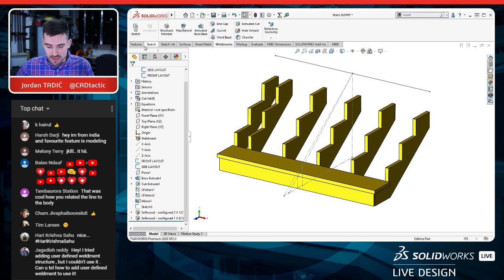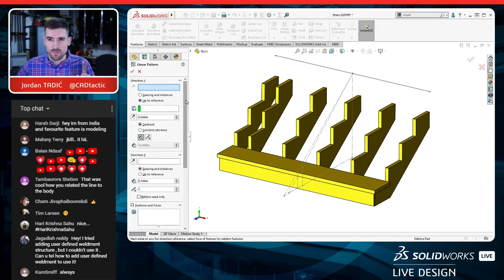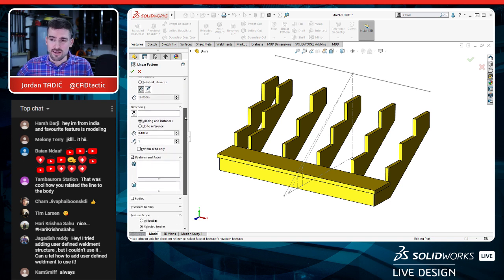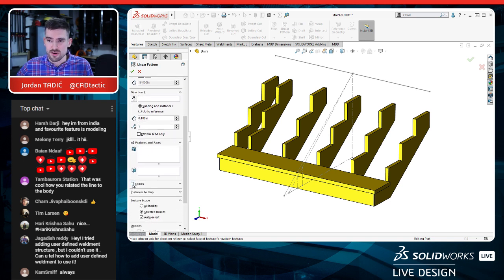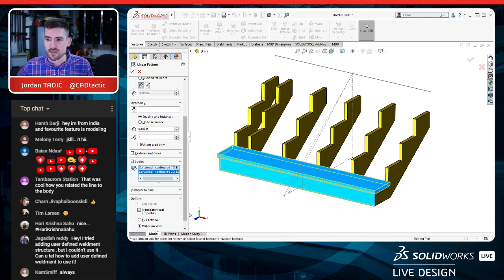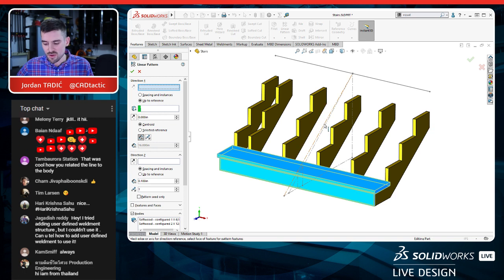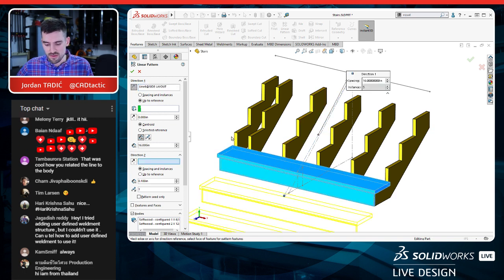All right, so linear pattern. Let's come back to the features tab. Remember, I like to select features or bodies in this case, because we're patterning the entire chunk of material, not just specific features of it. And for the direction, we're going to reference our layout sketch again. Again, I could select this edge, but the layout sketch will always be there. Why not just use that reference?